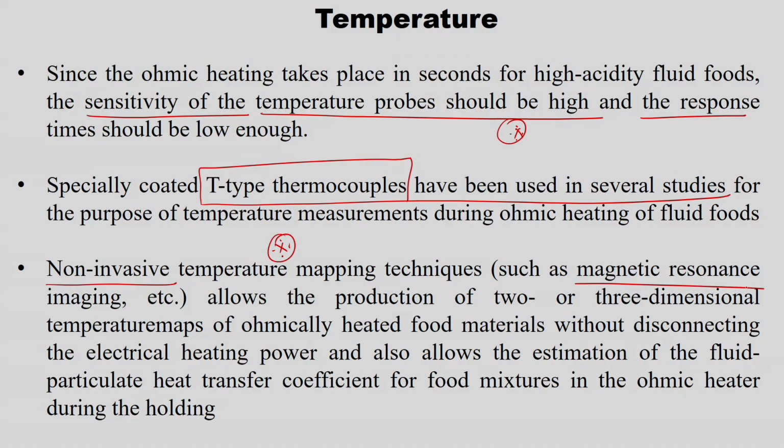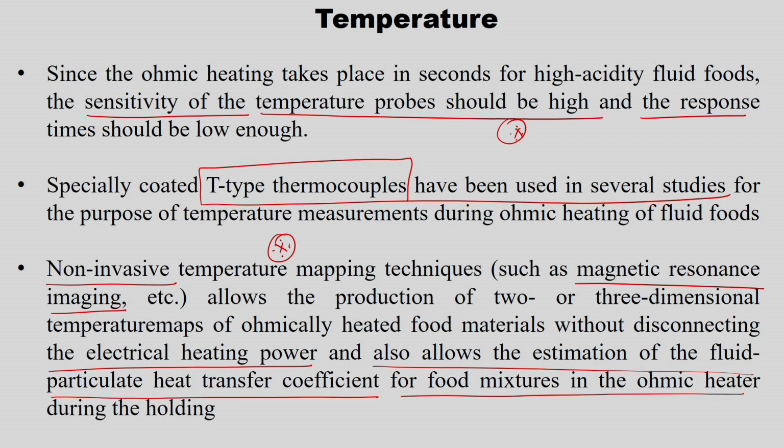One such is magnetic resonance imaging, which allows the production of 2 or 3 dimensional temperature maps of ohmically heated food materials without disconnecting the electrical heating power, and also allows the estimation of the fluid particulate heat transfer coefficient for food mixtures in ohmic heating during the holding period.